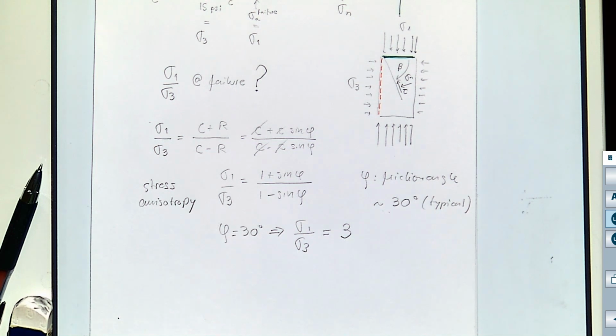And you remember that I told you to remember the number 1/3, because 1/3 will be important later on. Remember that with elasticity and with the Poisson ratio of 0.25, we said that the effective horizontal stress will be 1/3 of the effective vertical stress with no tectonic strains.